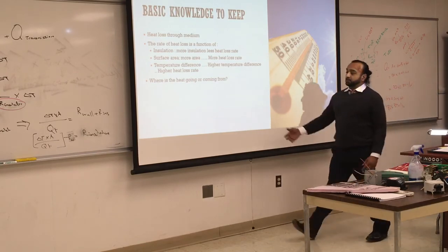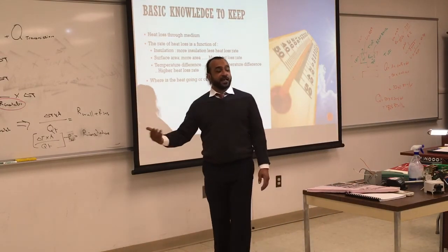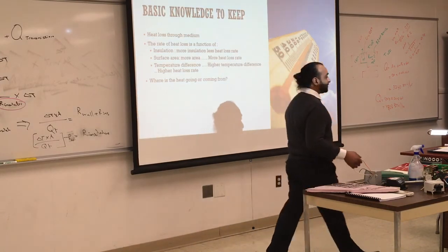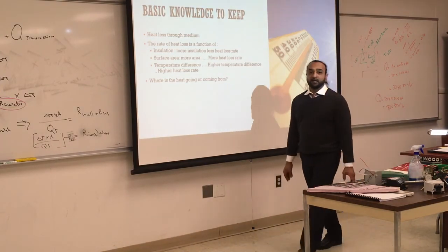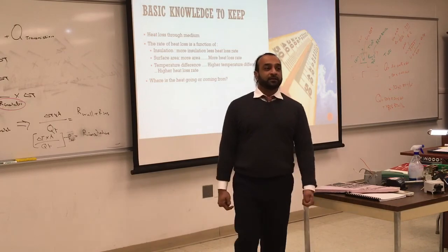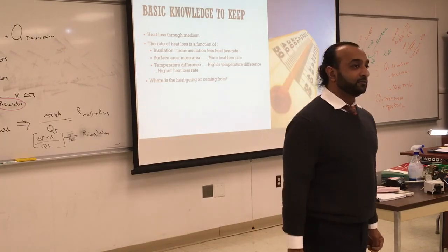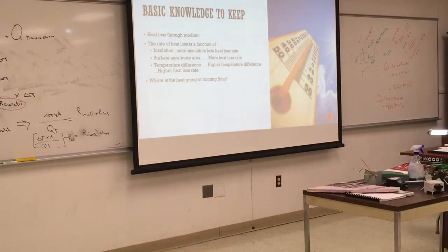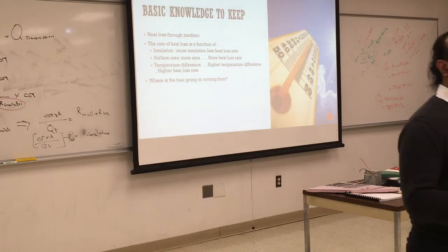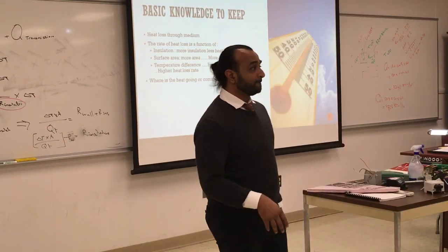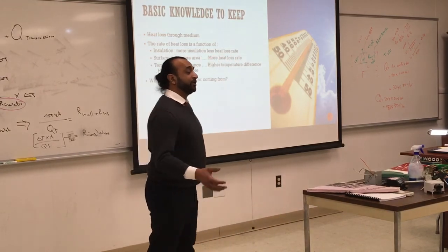Where is the heat going? That's important. Are you losing heat or gaining heat? For those who are taking the refrigeration course, when you do the cooling, what else do you have to account for? Are you measuring sensible heat, sensible temperature, or latent heat? We have to accommodate for latent heat, and that depends on the area, especially if you live in a wet area like Florida. You always have to counteract humidity.